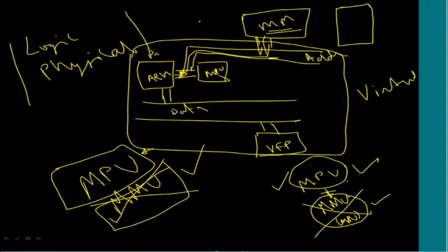Whatever memory it sees is the main memory's area. So if it has only 256 MB of main memory, then the program space will also be limited to this. We may have to write everything considering that there is only 256 MB of space in the system, and all the programs should fall within that. Whatever we decide about code, data or stack, where it should go, should be restricted to only the physical memory available in the system.